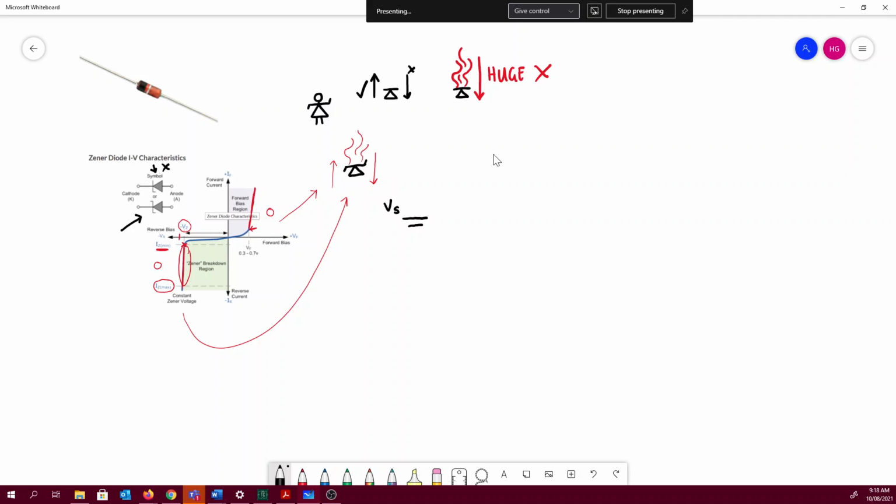And we've got something over here, alpha load. We've got something over here, and it's only rated for 5 volts. Right? Now, if we just hook that straight up to 9 volts, it might go pop. And so what we can do is use a Zener diode in this situation to control the voltage, or regulate the voltage, to 5 volts so that our thingamabob works.